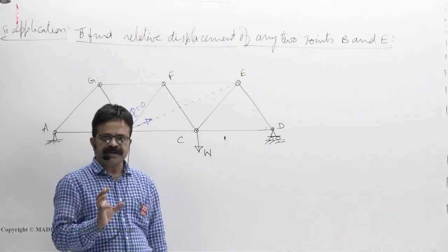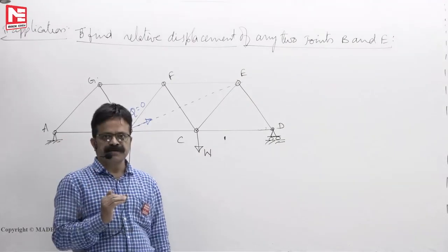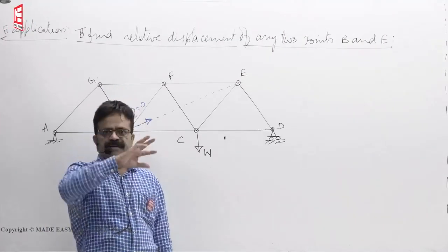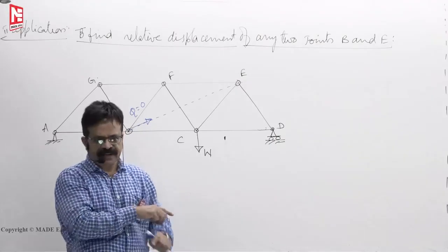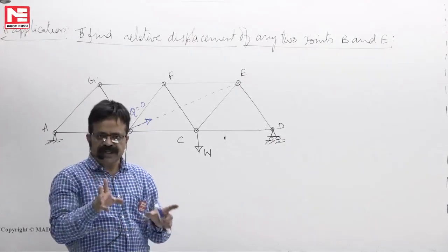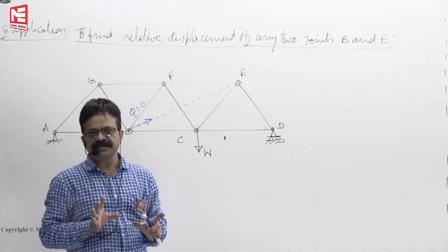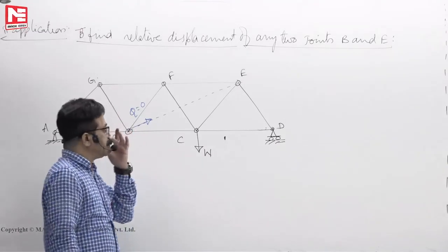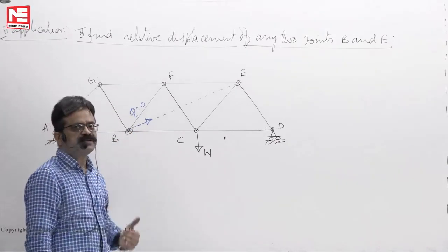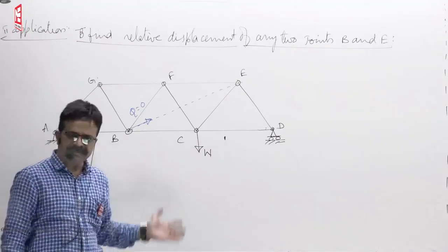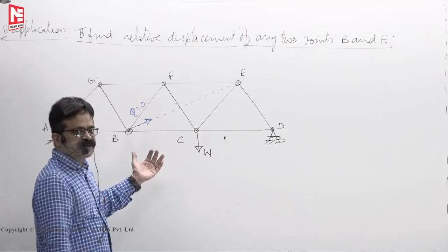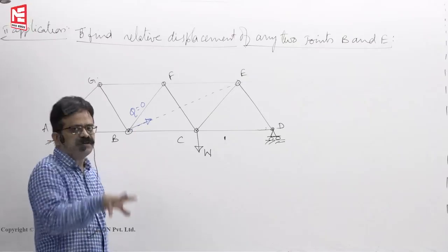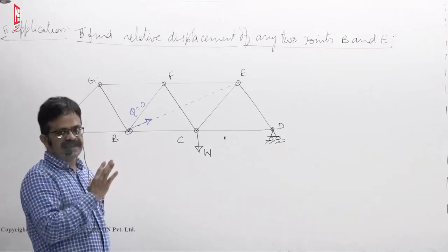Because first time when you are applying loads, it will go from 0 to W, remove the load. Then second time when you apply, again that starts from 0 only. Whereas in the energy expression, when you apply all the loads at once, only one time they start from 0 and go to their respective values. That's all. So only one time they will reach their respective magnitudes. But individually, when you apply 0 to W once, 0 to P1 once, 0 to X1, 0 to X2 like that, every time it starts from 0 only. The energy you get in that manner is very much less when compared with the energy you get when all loads are applied at once and increased gradually.